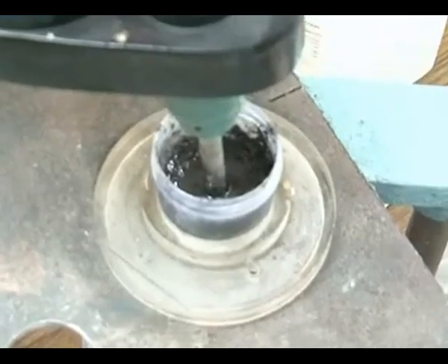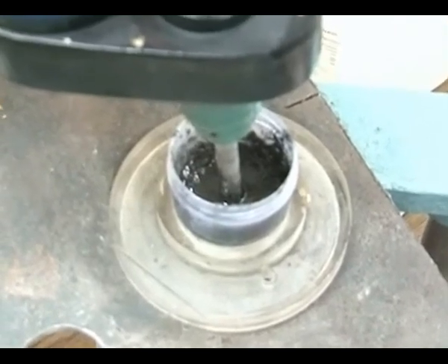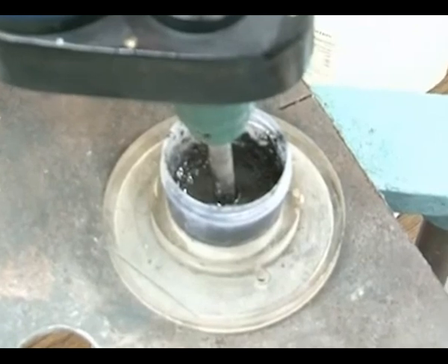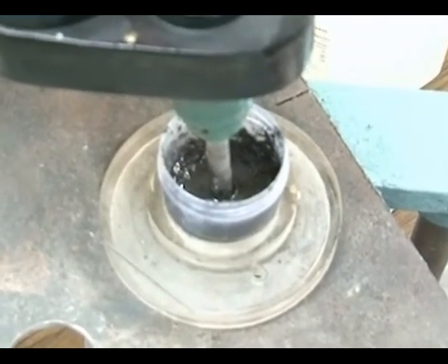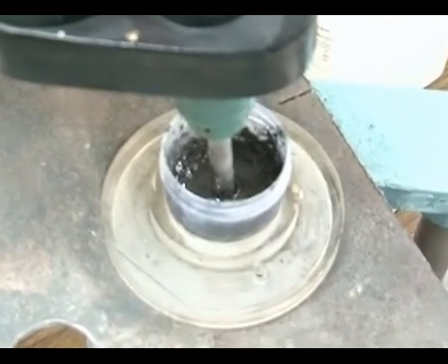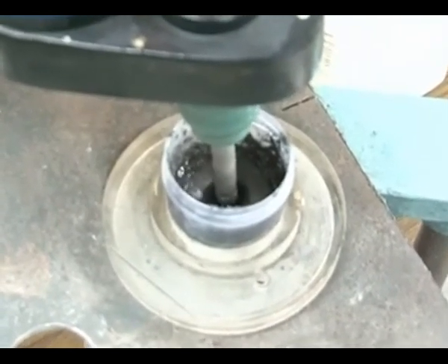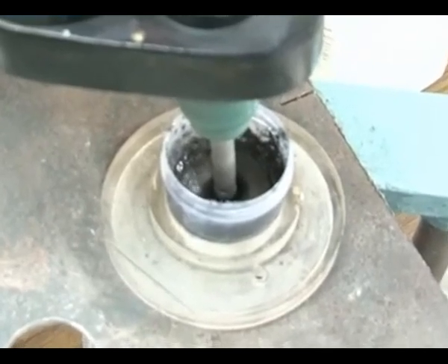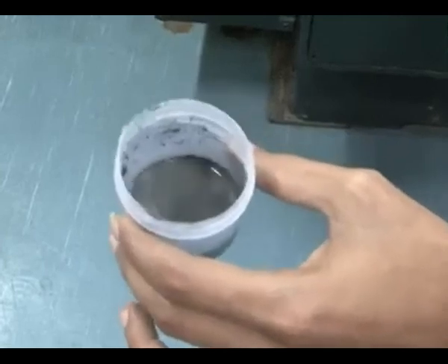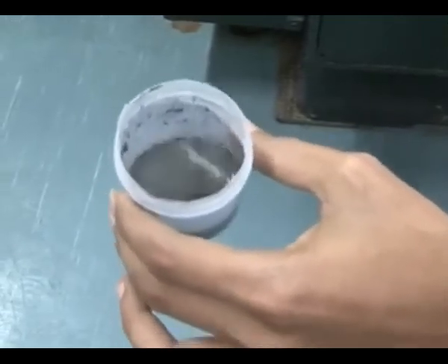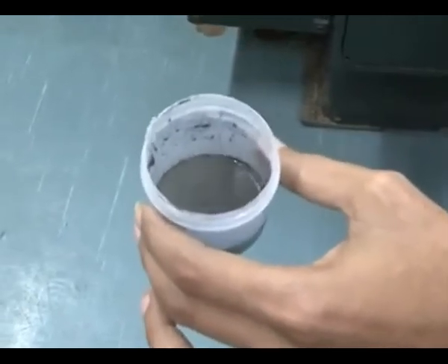All the constituents such as magnetic particles, abrasive particles, water and glycerol are mixed together in a proper concentration. After adding all these constituents, it is stirred for at least 1 hour to get it mixed homogeneously. Now you can see all the constituents of the MR fluid are homogeneously mixed. Now this fluid is ready to use in the MRF process.